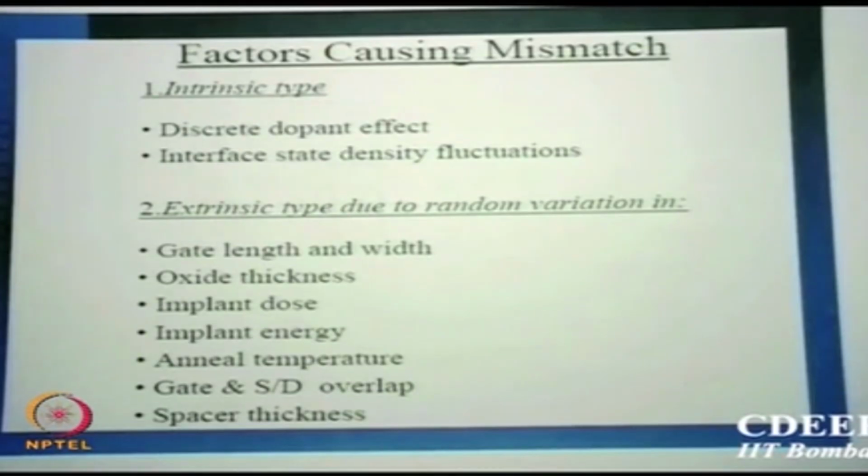Okay, as you reduce the channel, let us say the concentration, because of the Vt which you are adjusting, is such that, let us say 10 to the power 15 for the sake of numbers, and the channel length is less than 10 to the power minus 5 centimeters, 0.1 micron or lower. So what is the volume? 10 to the power minus 15. If it is lower, it will be 10 to the power minus 16, 17 per cc. So what is the number of carriers there? Less than 1, okay. So one cannot say with guarantee where the electron is, where the carrier is, okay.